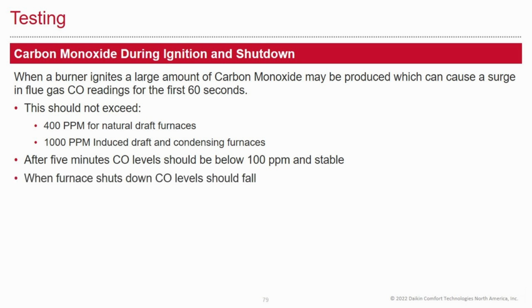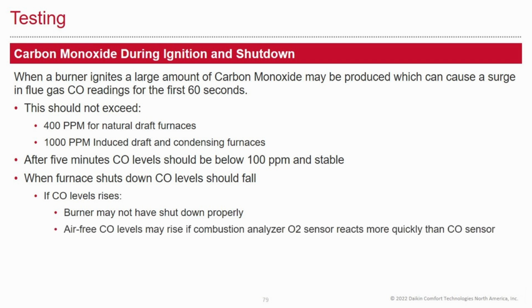When the furnace shuts down, the CO levels should fall. If the CO level rises, the burners may not have shut down properly. Air-free CO levels may rise if the combustion analyzer O2 sensor reacts more quickly than the CO sensor.